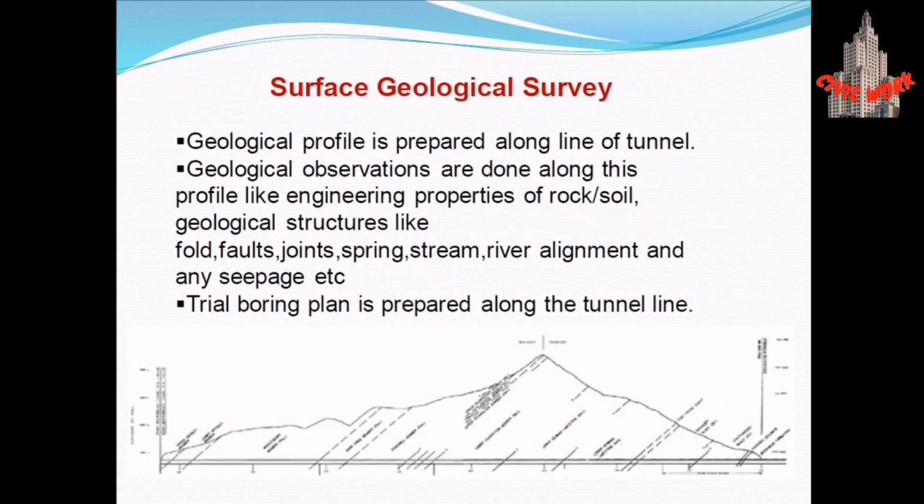Surface geological survey. A surface geological survey is an investigation of the geological conditions at the surface of the earth, typically conducted before tunnel construction. The survey aims to identify the geological formations, which means mapping the types of rocks, soils, and other geological features.